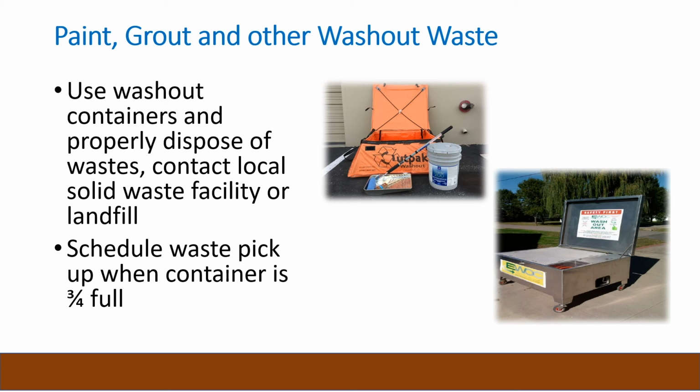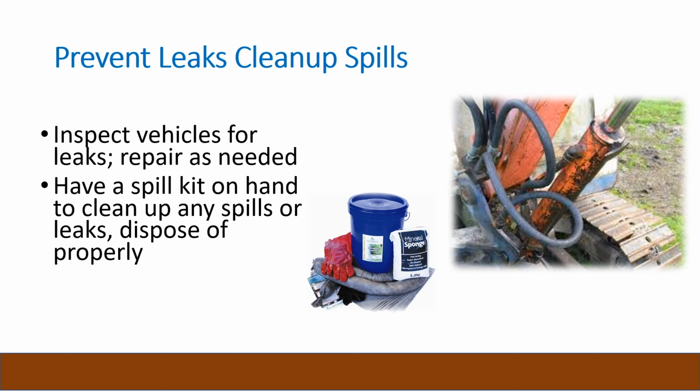Paint, grout, and other waste washout should be contained and not dumped on soils on the site. There are suppliers of lined containers that can be ordered online. Check on local requirements for washing out into the sanitary system inside of the building. Schedule pickup of the container when 3/4 full and cover when not in use so that it is not exposed to rain. Prevent spills and have a spill kit on hand.